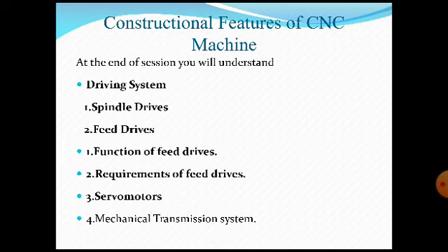As the name indicates, spindle drives are used for giving the rotational movement for the workpiece, and feed drives for the work table. That is what we are going to discuss at length in the subsequent presentations, and we will discuss in detail the function of the feed drives. When I use the word drive, it is nothing but a motor, for simple understanding.